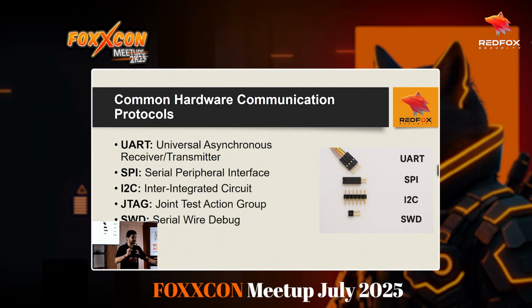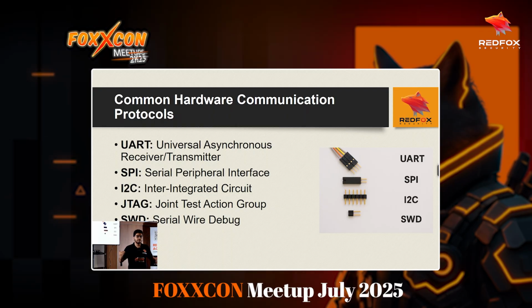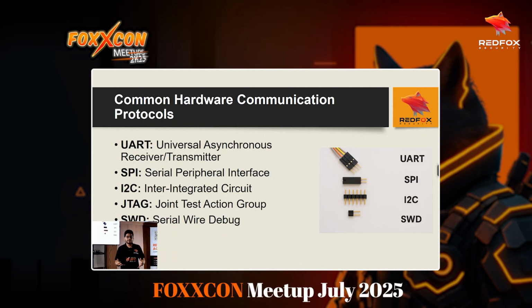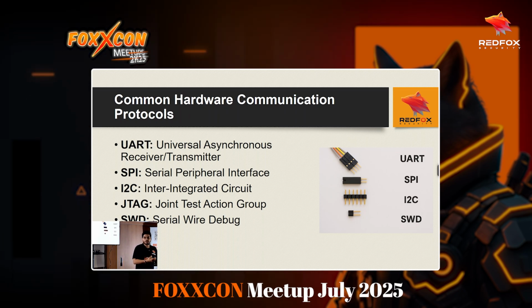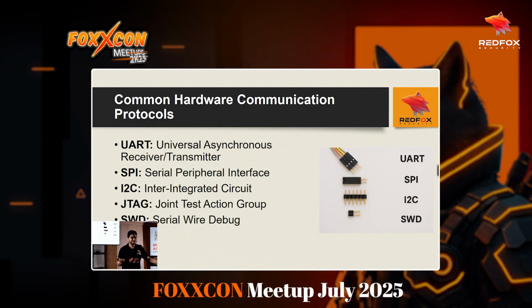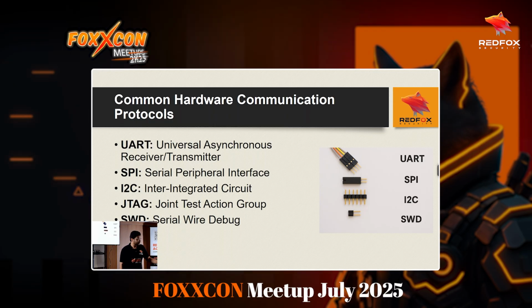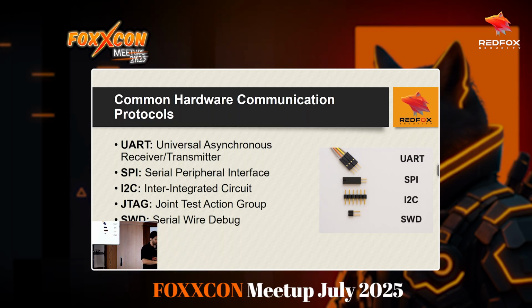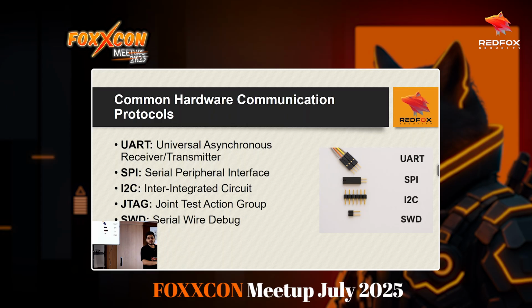So this is why serial communication is used as a debugging tool, but people forget that they need to remove it before production. That is one of the main things that you see when you look at pen testing a hardware device. These things should be disabled, because if they are not, then people will be able to get in very easily. A root shell is basically full access control. You don't have to do anything. There are variations of it. These are not the only serial communications that exist.